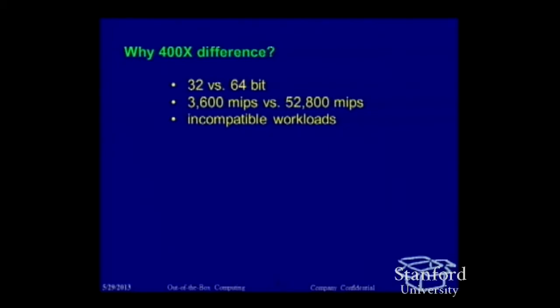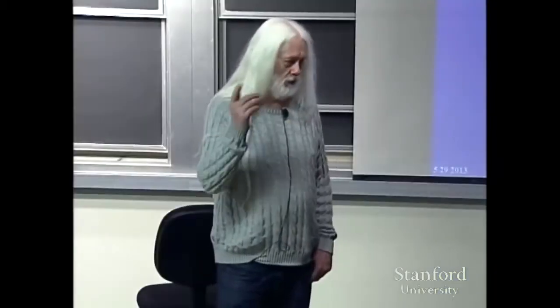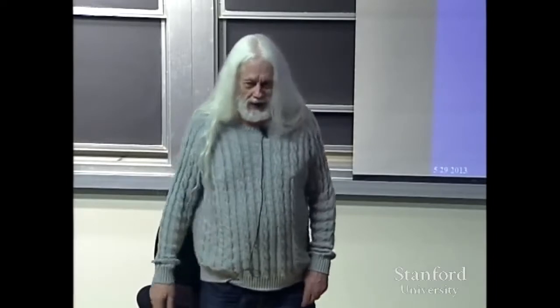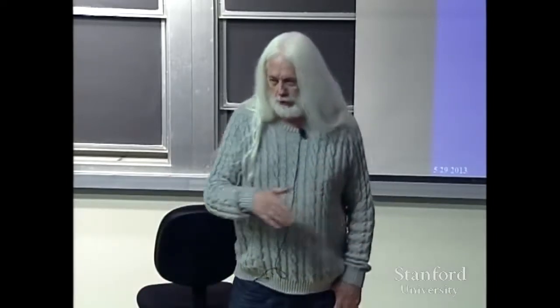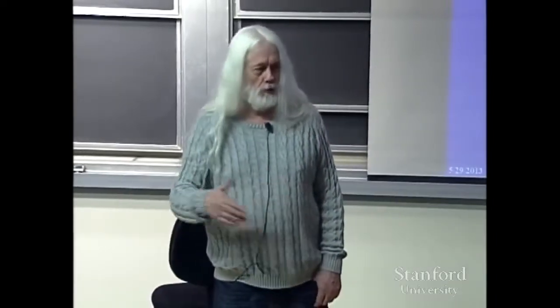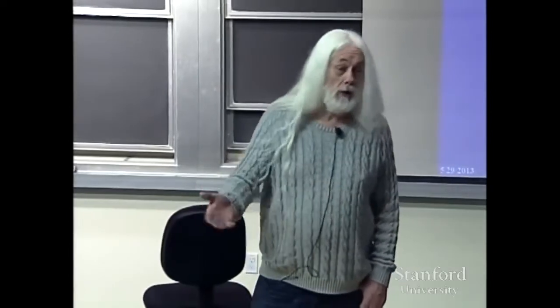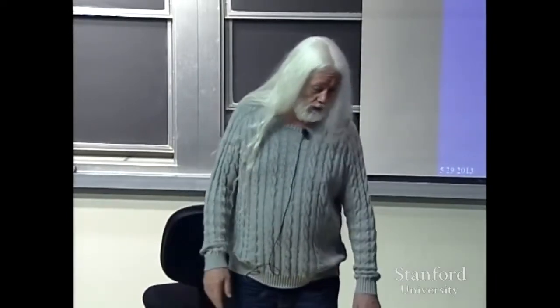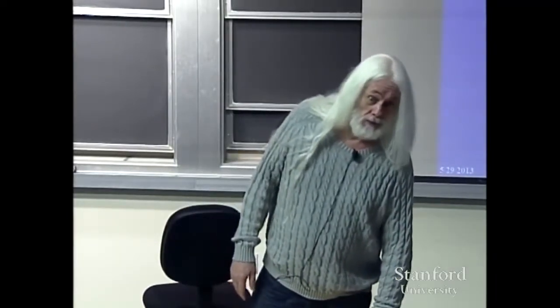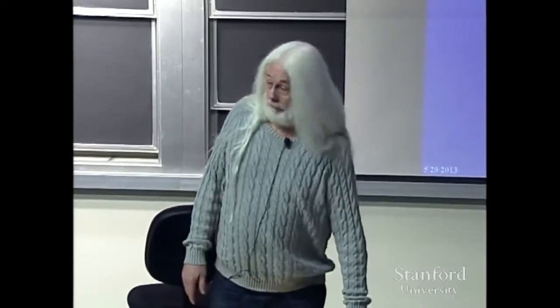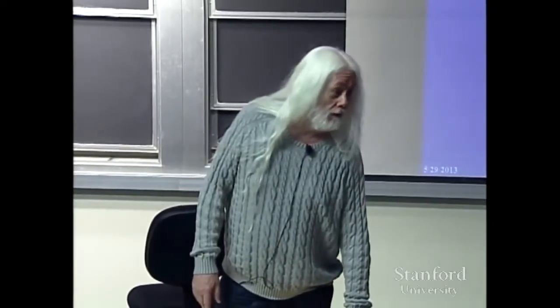The TI chip running on a general purpose workload is truly awful. It is designed for things which stay in loops forever, software pipeline loops, and code that is just full of random flow of control and random memory references, which is characteristic of your general purpose code. It tends to be very bad on that.